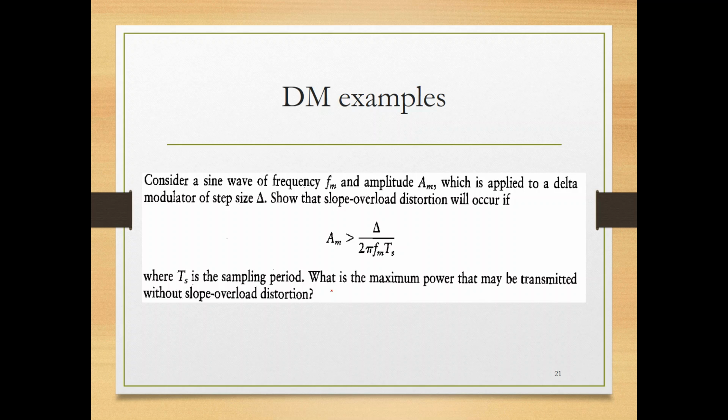And the last problem is error propagation. How to solve it? By integration, so that you can increase the slope of your function and make your current value dependent on fewer previous values. This is the summary of our lecture up until now, and we learned the law, the formula that we need to use so that we can avoid overload distortion.